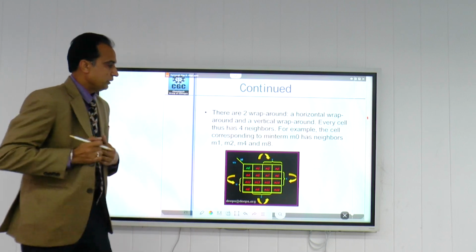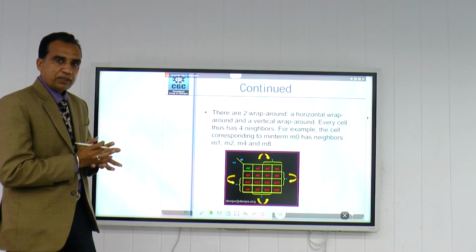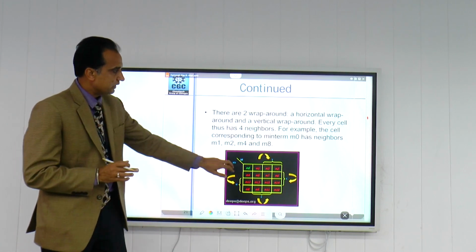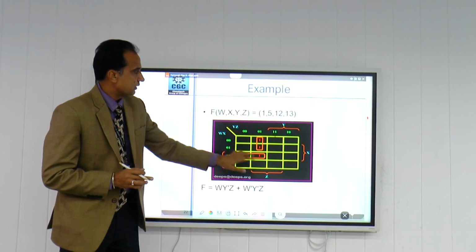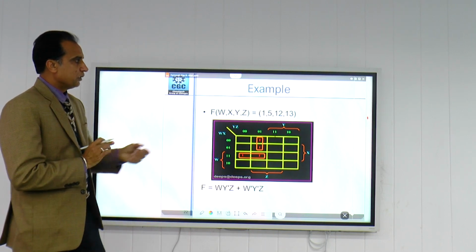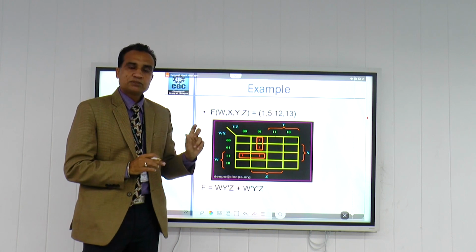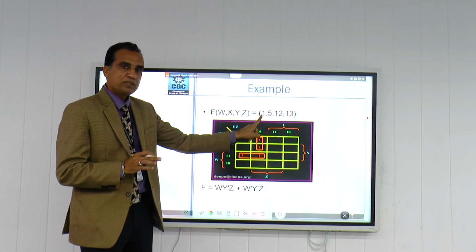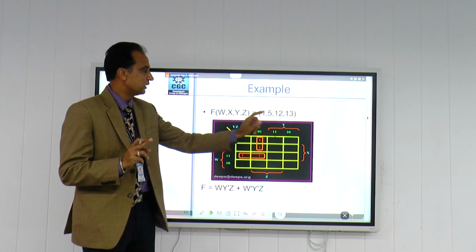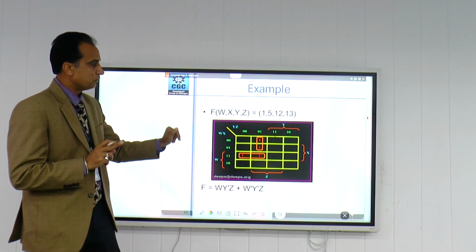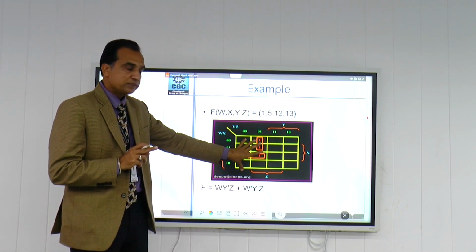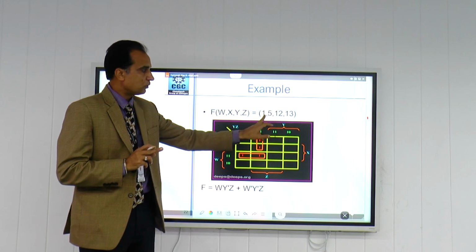As I already explained, we can fold the K map so that the adjacent or the corners can be converted into a single group. This is the equation which we are going to solve with the help of a K map. Now, equation can be given in terms of min terms. The first one means first min term, fifth means the fifth min term, 12th means 12th min term. Now, how do we fill the K map according to the equation? We use four variables, means total 16 square grids are there. We have to fill the K map according to these values.